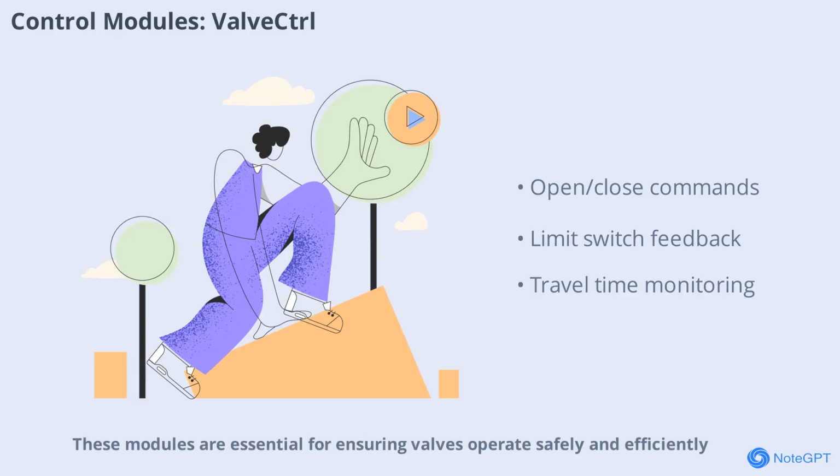These modules are essential for ensuring valves operate safely and efficiently. During your project study, verify that each valve control instance is properly configured and that all feedback signals are correctly mapped to the corresponding I/O channels.